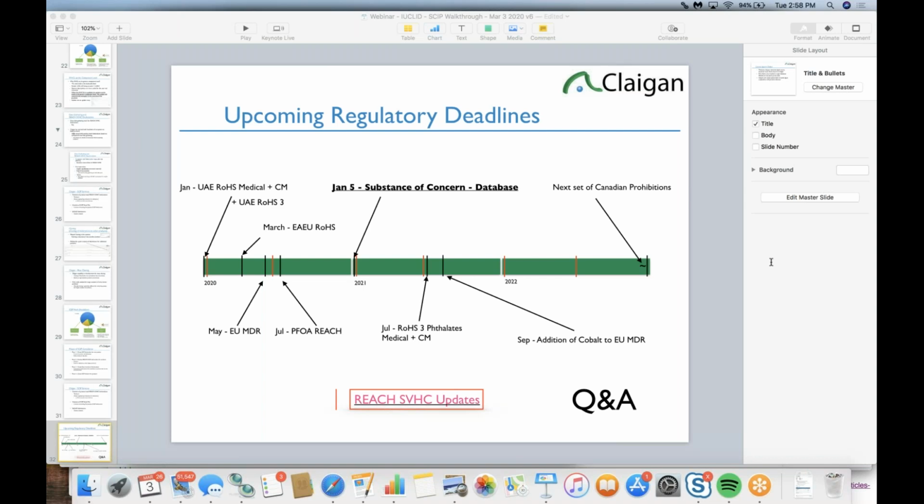But normally what we do is we list lead in solder, or lead in high temp solder, and then how many components have it, and close enough. As long as we identify high temp solder and say any individual product may vary the number of high temp solder parts it has with the SVHCs, we'll say high temp solder, best estimate is 5 parts. Then you have to list this. The lead solder, whether it's because not RoHS compliant or because you use high temp solder, so exemption 7A for RoHS has to go in there.